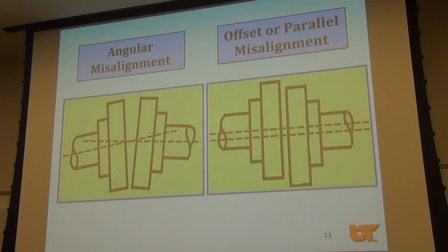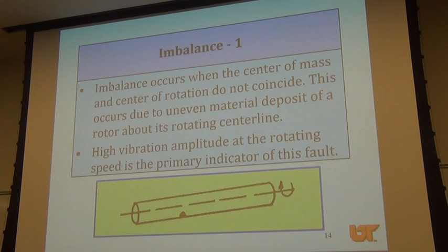Accelerometers are the devices that you use to measure the force acting on the bearing. It depends on the direction of the force, right? The force could be acting in the axial direction, or vertical direction, or horizontal direction. So you need to place accelerometers in general in all the 3 directions so that you can measure the vibrations coming from various directions.